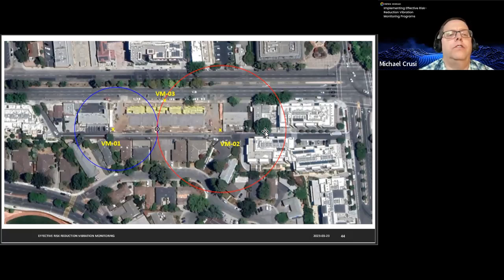Do you take into consideration vibration frequency and potential for resonance when completing a vibration monitoring plan, i.e., if rock chipping occurs at 100 hertz, vibration resonance is less likely in a residential structure versus 15 hertz from hammer pile driving? Yes. So looking at the construction equipment and the types of vibrations that they produce is part of the assessment that you should be doing.